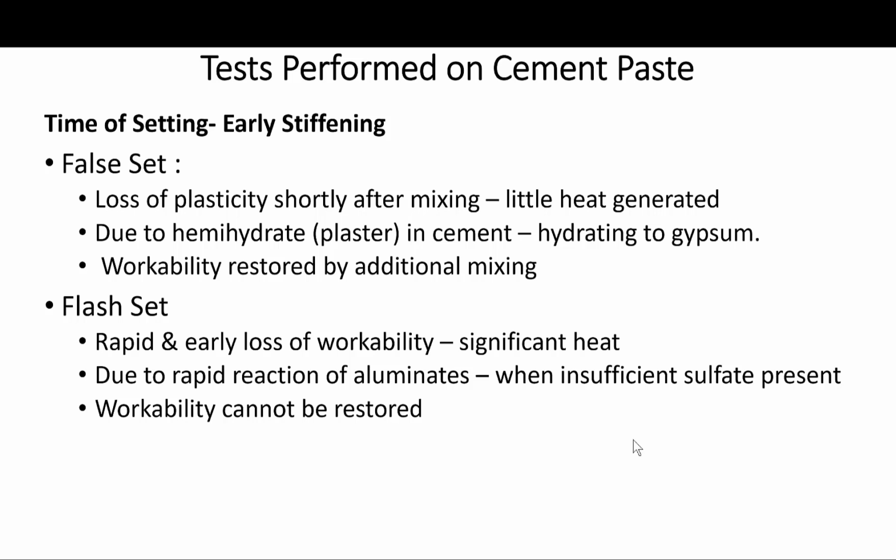This is due to the rapid hydration of C3A when insufficient sulfates are present in the cement. Remember when I talked about the hydration of C3A and I said the sulfates are added to control its hydration to prevent flash set. So the cement has to be properly sulfated in order to prevent this phenomenon.